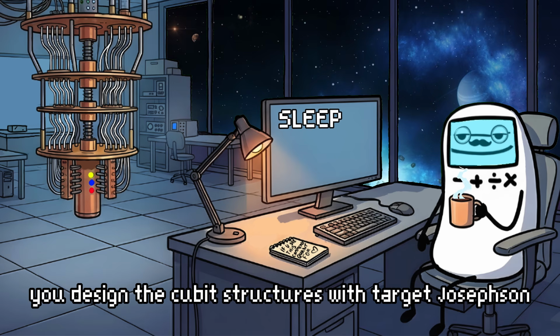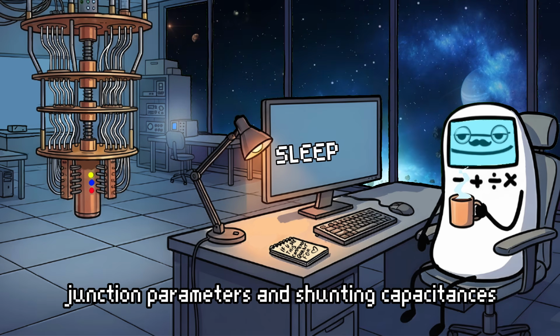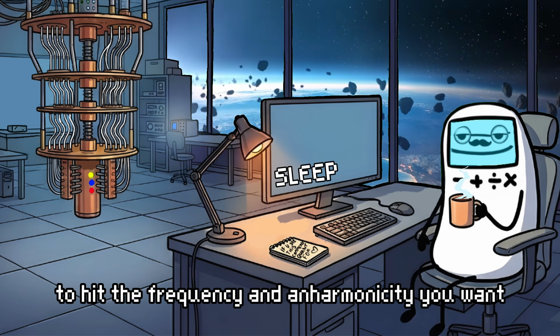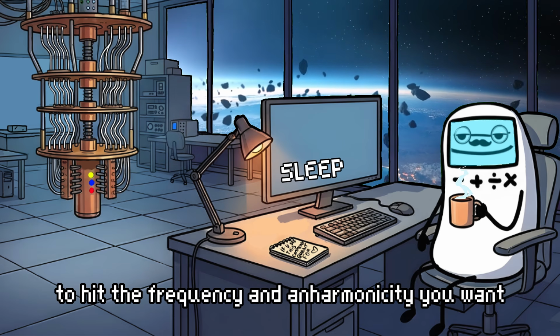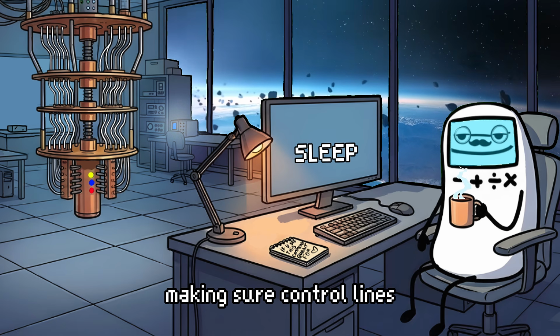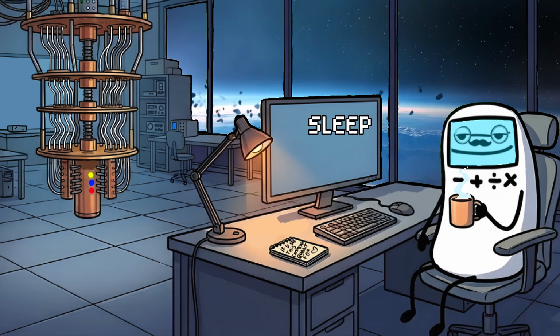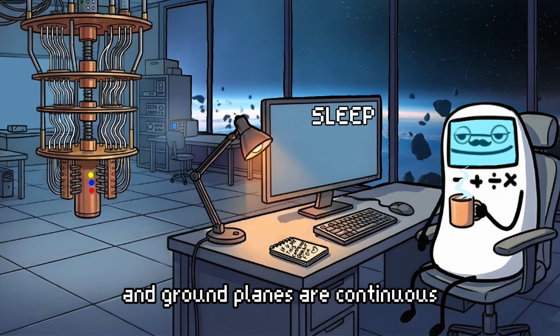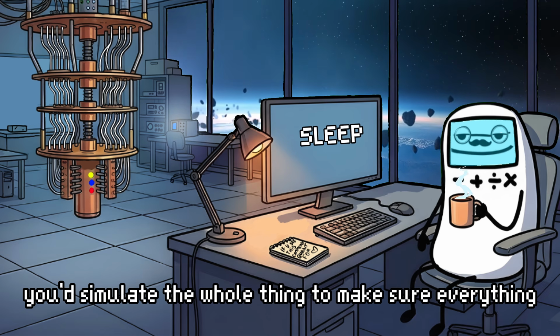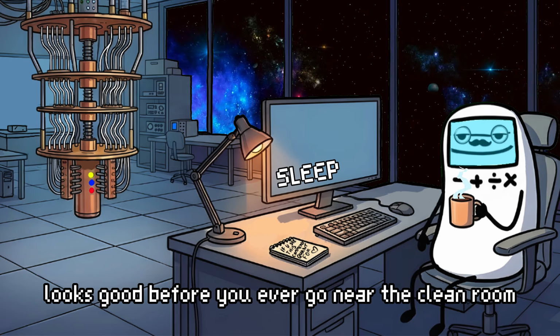You design the qubit structures with target Josephson junction parameters and shunting capacitances to hit the frequency and anharmonicity you want. You'd lay out the whole chip, making sure control lines don't cross each other unnecessarily and ground planes are continuous. You'd simulate the whole thing to make sure everything looks good before you ever go near the clean room.